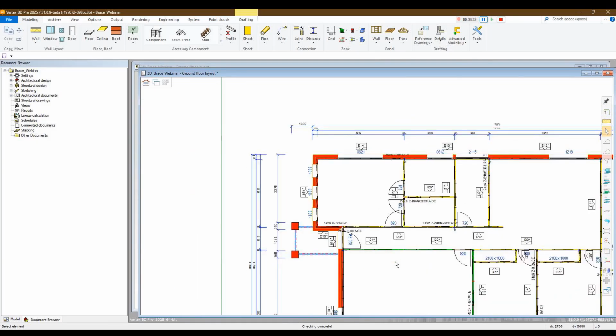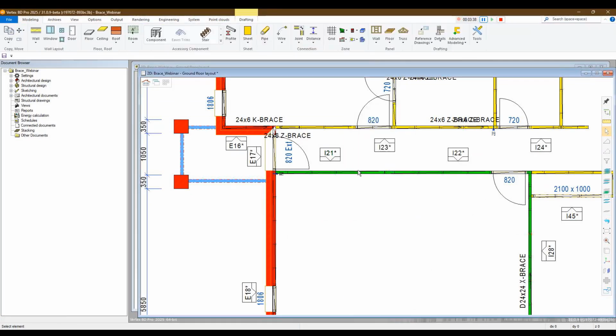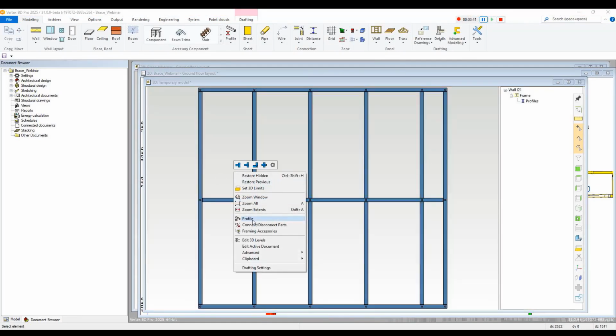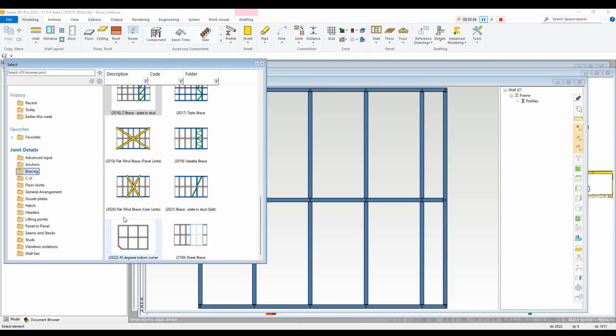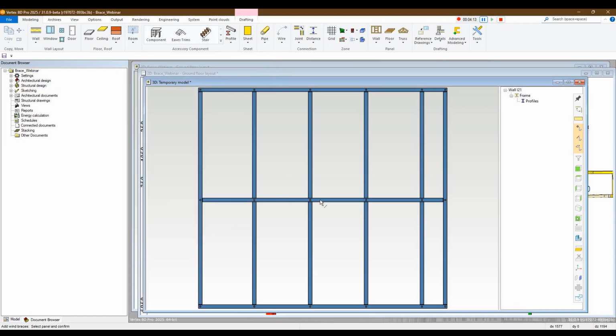And if we're looking at a strap brace, I'll go to edit this one, and we'll look at using the strap brace with the user limits. You can use this one as well, but we'll just use this one for now. You also have the option under the strap brace to have different values. If it's a single brace, being either on the external or internal side, it doesn't matter, it'll be a single cross brace. Or you have a double cross brace using the both method. In this particular case, I'll just do a single.